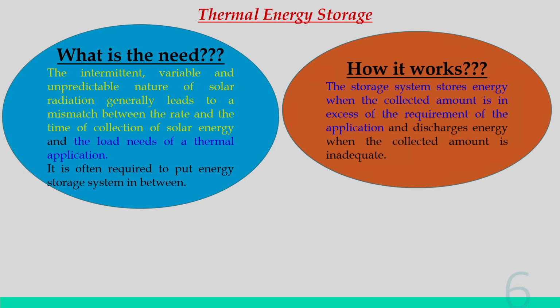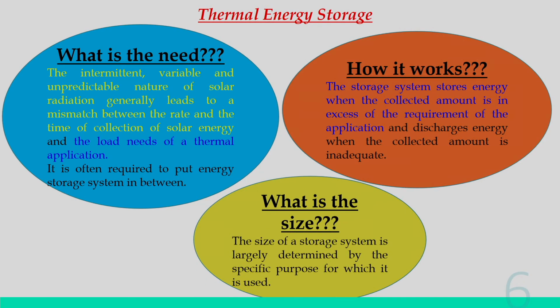Then for that condition we need some kind of autonomy. Okay? So, how does it work? The storage system stores energy when the collected amount is in excess of the requirement of the application and discharges energy when the collected amount is inadequate. Okay? So, now look into the sizing.